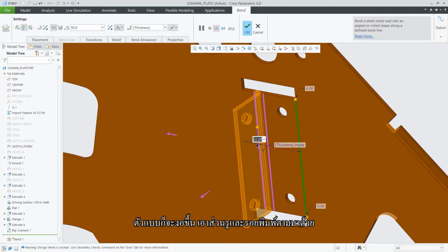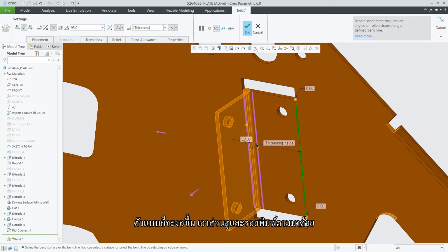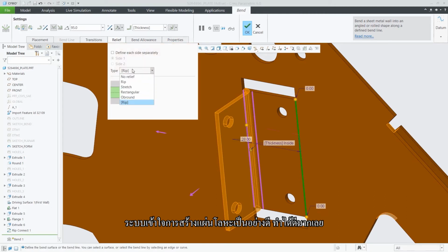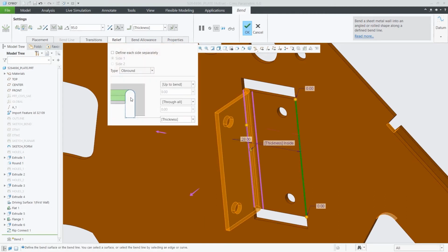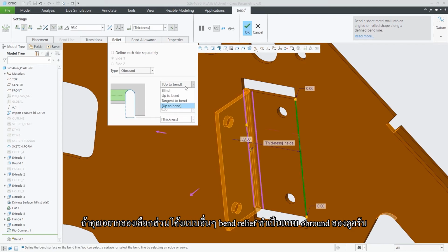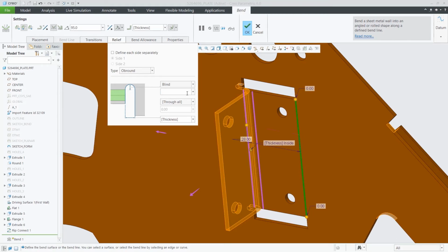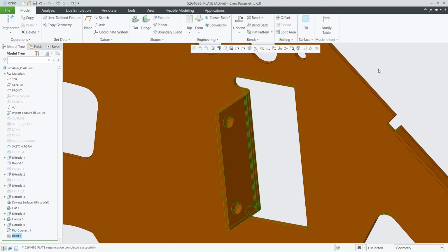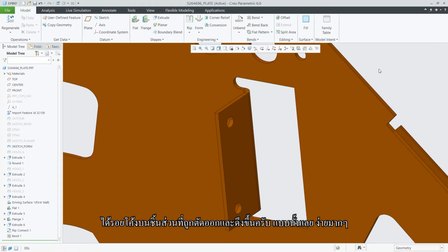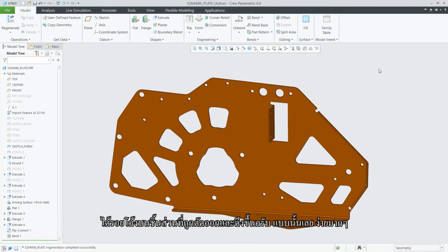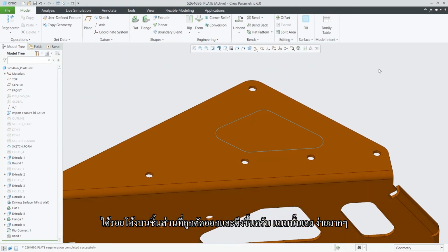So now it takes that geometry, including those holes that are punched there. It understands how sheet metal is fabricated. Again, best practices, do you want to put in different types of bend reliefs? In this case, yeah, let's do some round cutouts there. So go ahead and set the size the way I want, the thickness, something like that. So now I've created a bend on material that I've ripped and pulled up. So just like that, makes it real easy.